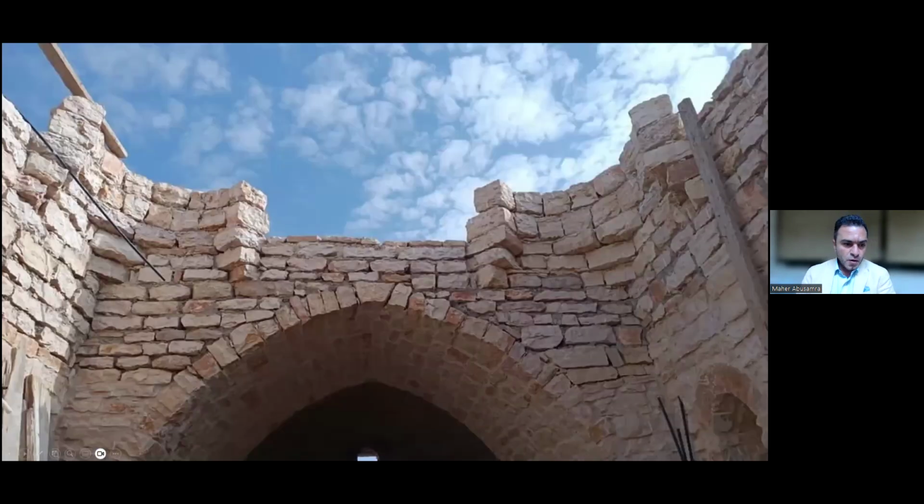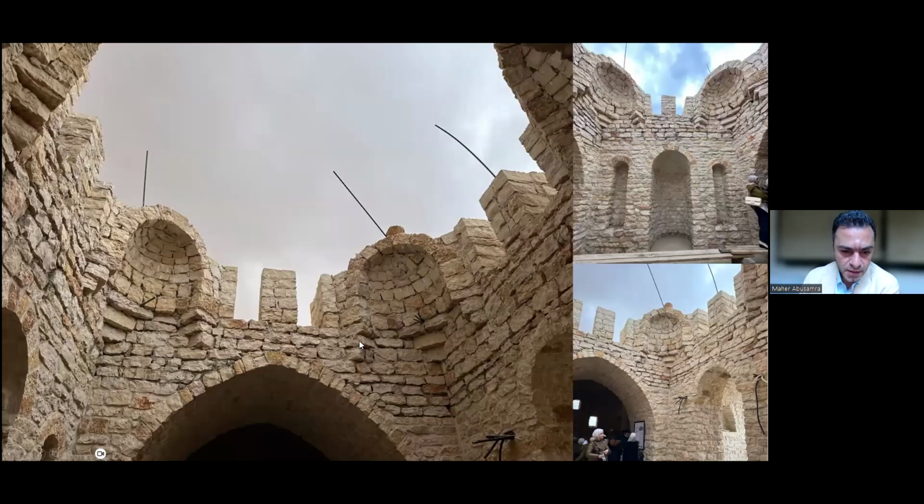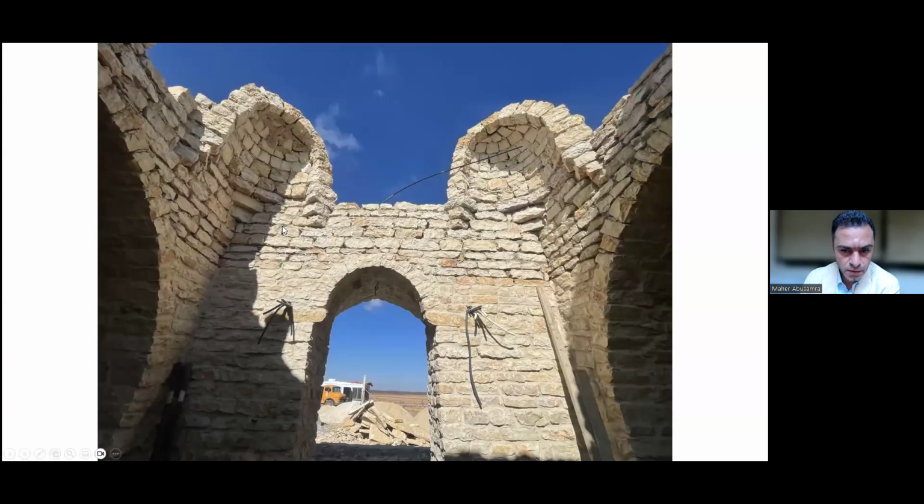Details. In this picture, we can see the squinches, which are carried out not as stalactites, but like cantilevered triangles, big stones going through inside, one above each other, to get the octagon shape. And here, this is the squinch and the mihrab elevation side, the entrance, and we can see here the squinch carried on those three levels of stones.